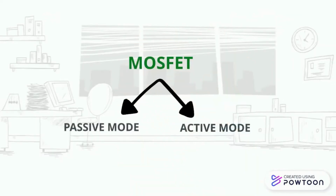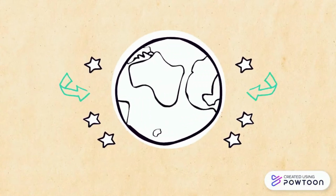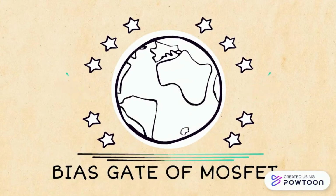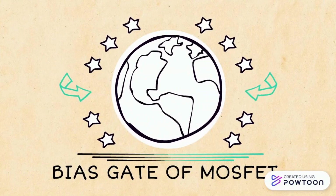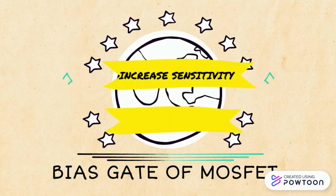MOSFET detectors can be used in a passive mode and also an active mode. Passive mode means zero bias on the gate during the irradiation, and active mode means a positive bias on the gate during the irradiation. Bias on the gate of the MOSFET detector increases the electrical field in the gate, leading to reduced recombination of electron-hole pairs created by ionizing radiation, and hence increasing the sensitivity of the MOSFET and also the linearity of the response.